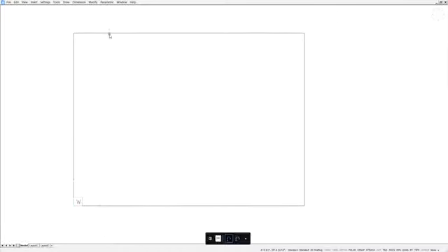And I can continue working on this, and notice, I drew this rectangle with the quad. If I pass my cursor over an object like this rectangle, I'm not even selecting the rectangle, I just pass it over, and BricsCAD knows the last tool that I used with that type of object. So it displays very quickly by default right there on the quad, as well as other things such as the layer and color, which I can hover over and change right there. But if I hold the cursor over that tool, because maybe that's not exactly the tool I want, it will display the most recent 6 tools there. So I can select from the most recent 6 tools that I used for that type of object, a polyline.